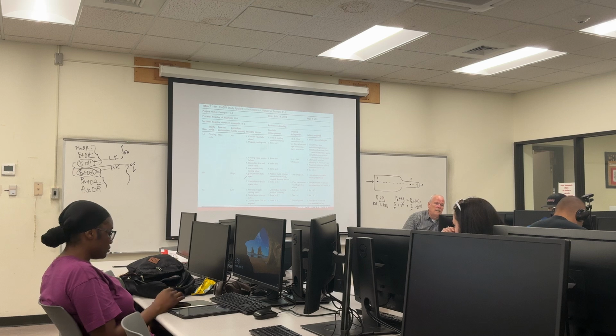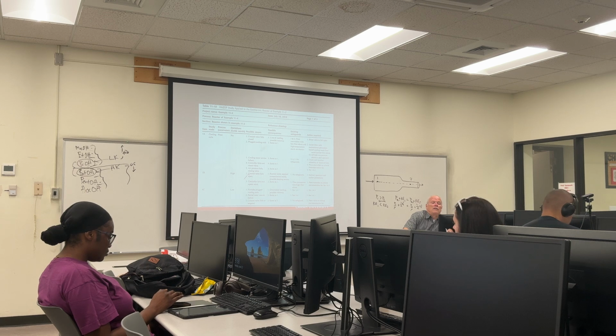Let's see what we've got here. So, cooling flow, no flow. Loss of cooling, possible runaway. And then, in the HAZOP, they say, well, what are the existing safeguards, you know, what action could be taken? And then you also have to say, well, how did it happen? Because you're trying to come up with scenarios.